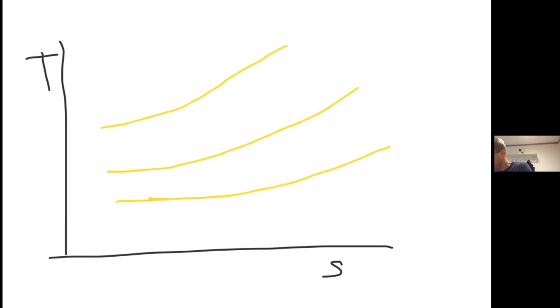Then we always have the isentropic compression, like here. Isentropic, so that is where you have a constant S. So delta S is 0. That's isentropic, and that's the ideal case. And the ideal case is that you can also let it expand along the same line, so it's reversible. It's the isentropic.